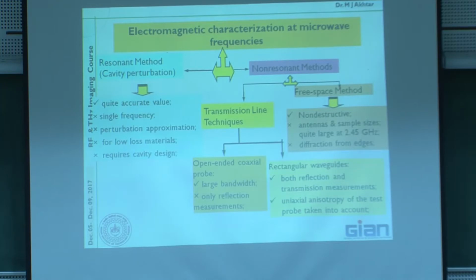On the other hand, non-resonant methods mean that with one measurement, you can obtain the property over a wide frequency band. This works very fine because there you measure the reflection and absorption coefficient over the band, and then at each frequency you try to obtain permittivity, even permeability if the material is magnetic, using some algorithm. Now our aim is to use this for imaging. Or let's say even for characterization also. So in this case, let's see how it works. In resonant methods, it's simple.